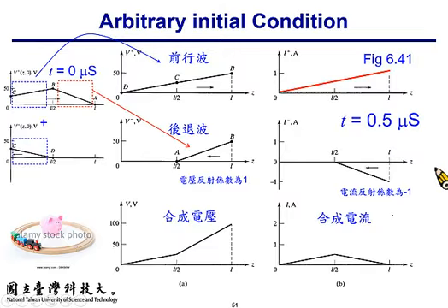So we get the I plus signal and I minus signal after the time delay. And the very last thing is adding up the V plus and V minus, I plus and I minus, to synthesize the total voltage and the total current.